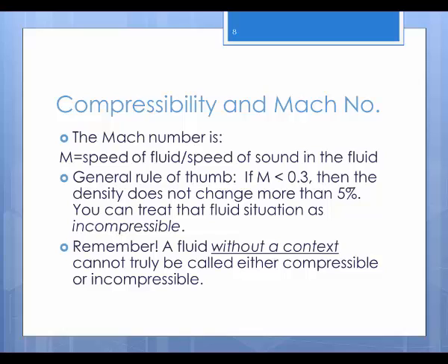And this number changes according to the identity of the fluid because the speed of sound in every fluid is not the same. So it makes it nice that you just have this one number, the Mach number, and if you can evaluate that number for air or water or oil or sludge or whatever it is that might be moving quickly, then you'll get a pretty good sense of whether the flow conditions tell you that I should treat this flow as compressible and not incompressible. Or I know that the Mach number is pretty low, so I'm pretty safe just saying it's incompressible and treating